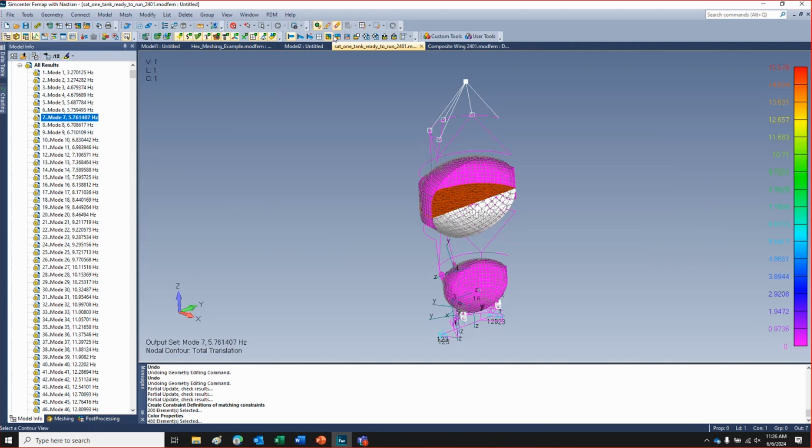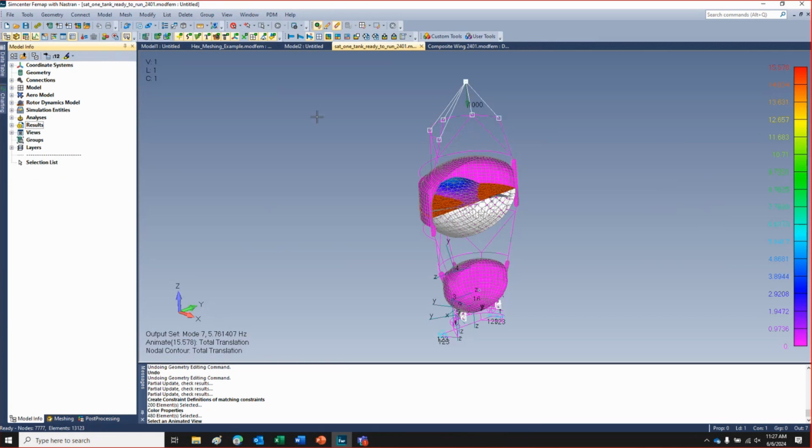Just so you can kind of see what the sloshing looks like. I'm not really going to go into it here, but this was like 2 tanks, very spacecraft-oriented type stuff. But you could also use it for other things, just anything with a fuel tank essentially. Down here is solid mesh. The thing is actually meshed with shell mesh. And then you create a region, an incompressible fluid region on the free surface of your fluid. If it's fully filled up or whatever, there's actually an option for that on the thing itself.